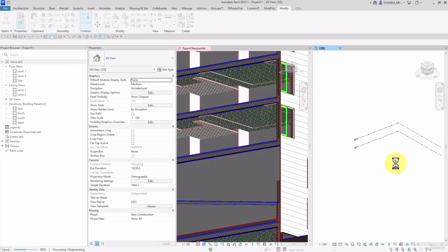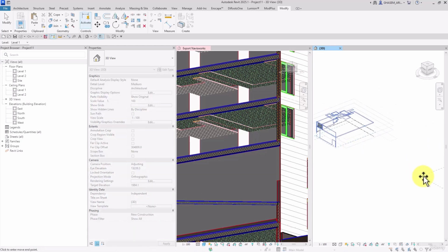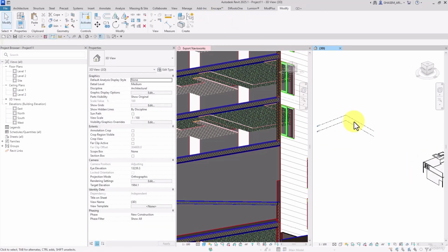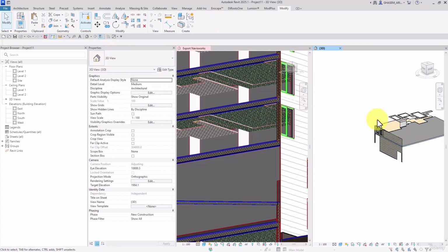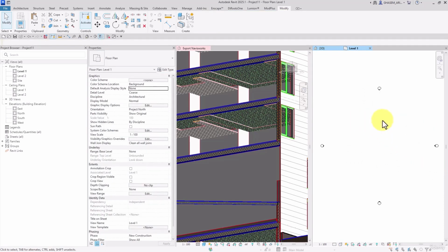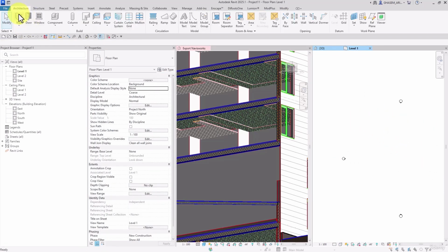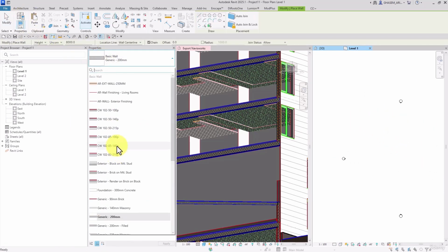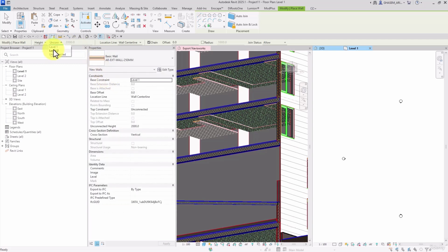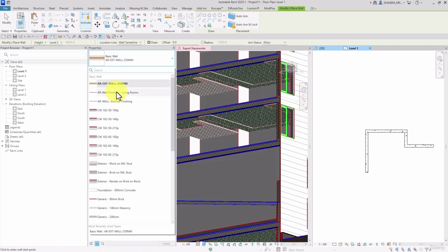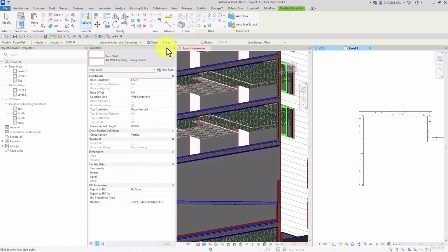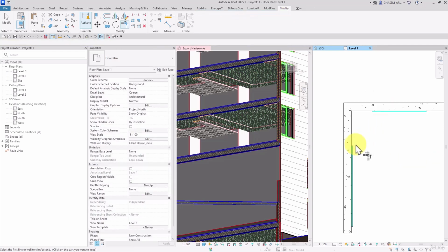Afterwards these types of elements will be imported here, so then we can use them, finish to save the changes, and note that if we have any selected elements, we can select them and then change the types, or we can delete the imported elements and then we select the wall. Afterwards you'll see that the new type is accessible in the type selector, that you can start your modeling by this way. For instance, for the finishing walls, like this way.